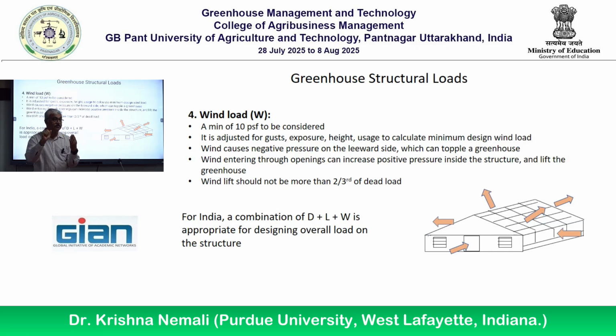Snow load is another 15, right? So that's 35, and I'm adding another 5 or 10 for wind. This is 45 psf. If you have Google, you can convert psf, pounds per square feet, to kilograms per meter square. It's a very easy conversion. But I'm talking about 40 to 45 pounds per square feet.